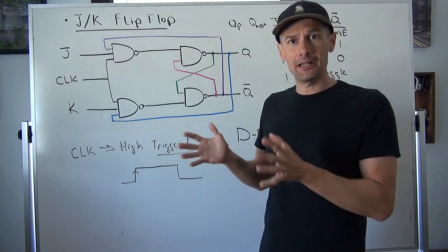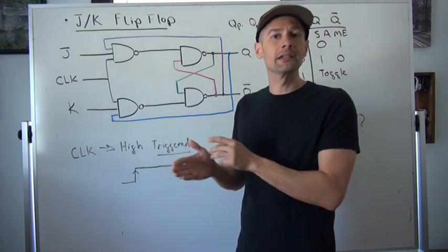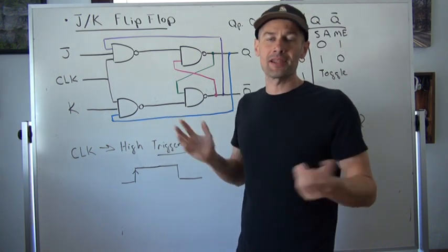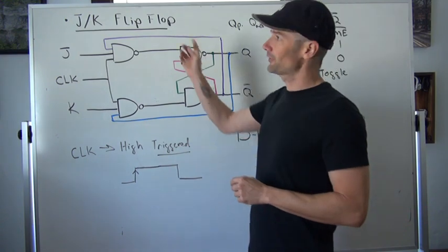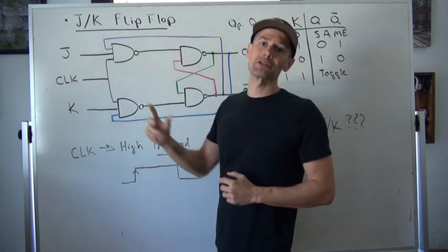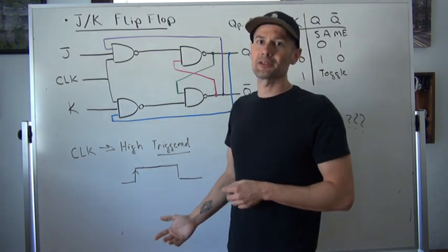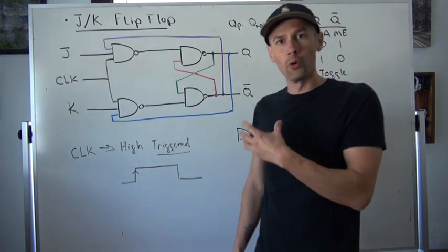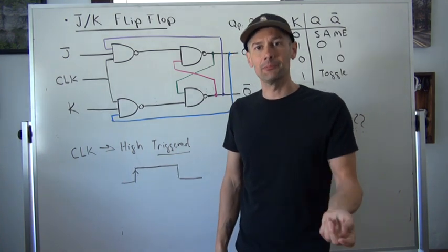The D latch, as long as that clock cycle is high, can change its output at any given point during that high cycle. Generally, when we say flip-flop, we're introducing the concept of edge triggering for the clock cycle, a more synchronized way in which we can change the output.